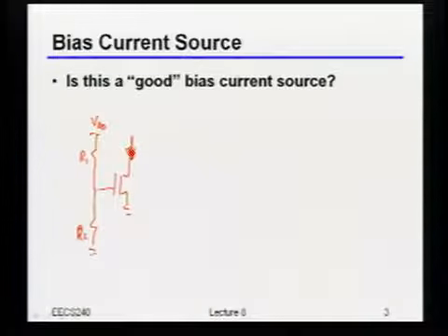There's obviously a long list of problems here, so just start throwing them out. You have a power area trade-off with the resistors. Okay, that's true. That's actually not the worst thing, but yes. So I'm going to spend some power on those resistors. I agree with that. Maybe I can make those resistors huge, but yeah, I agree. That's annoying. Anything else that I think is maybe much worse? Relying on one transistor is going to get you really horrible matching.